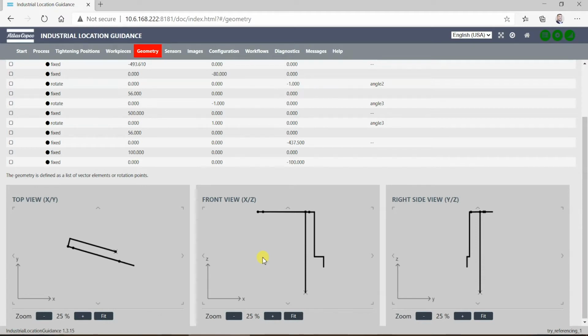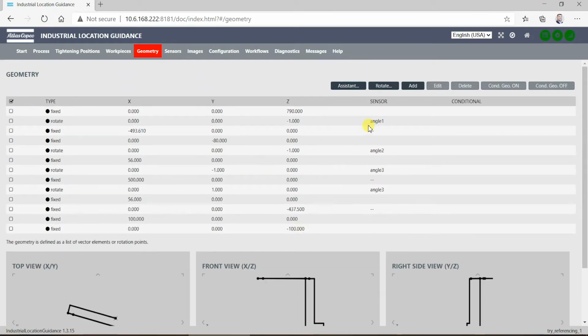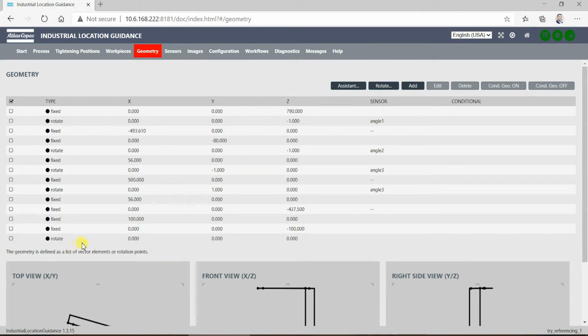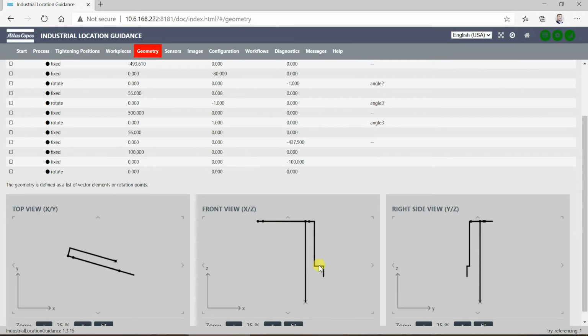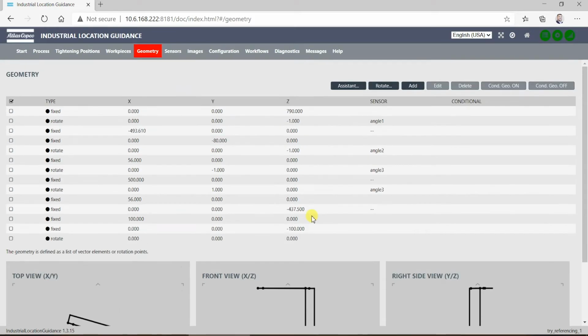The other thing that you're going to want to do in here is you can see this is your down angle. So this is basically the arm and then the tool holder. And this is going to account for where the tool is at in space. But let's say you have a longer than standard socket that you want to account for, because the encoders are not necessarily going to pick that up in space. What you can do is actually add a spot here, and then you can account for that directional change. So from here, then you would expect it to go out and then down. So this gives you the ability to then add in that longer than standard socket.